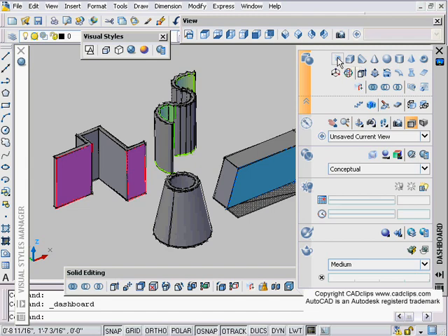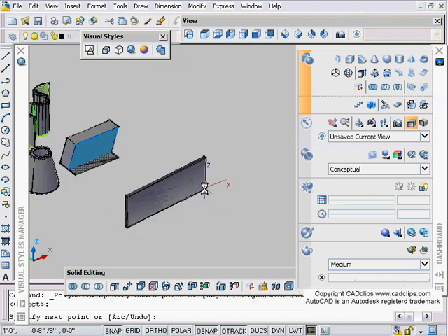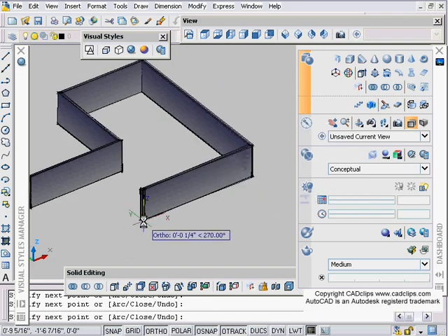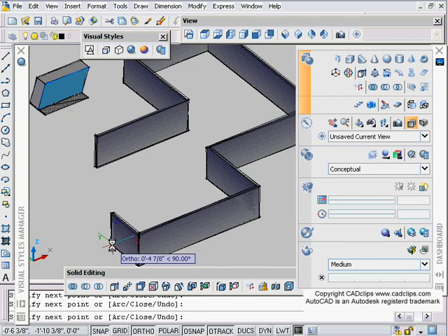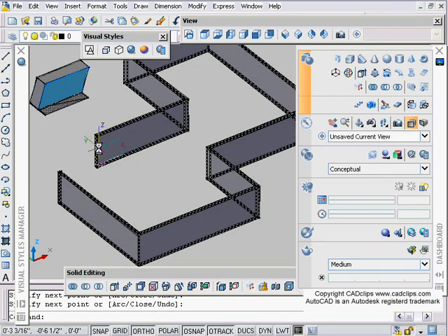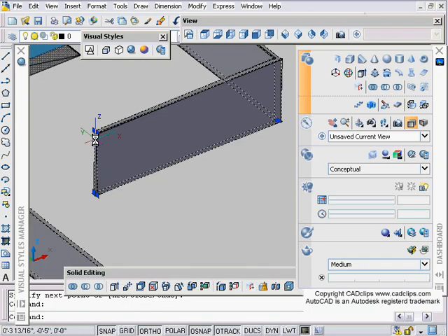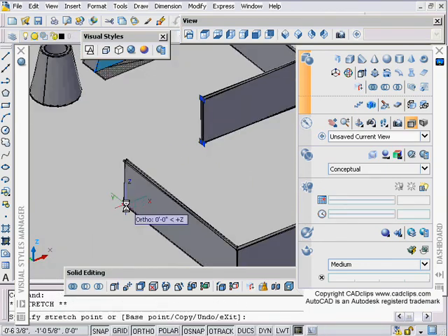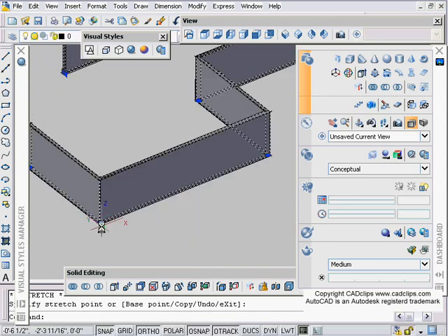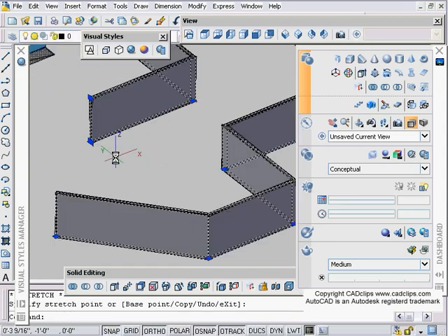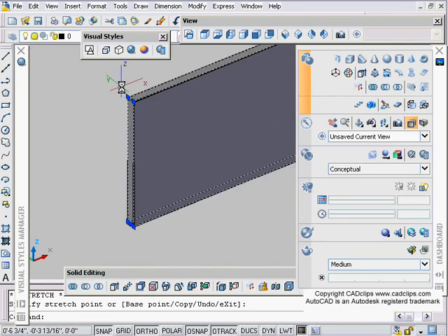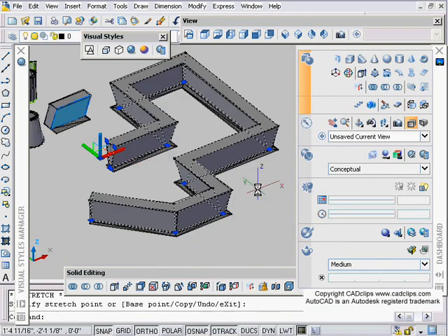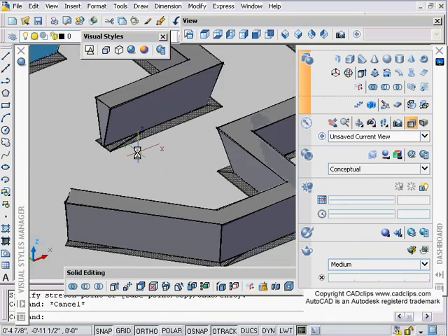Really easy stuff, and if you want, you can just pick Polysolid and start to draw. You can use your ortho, etc. Polysolid just kind of draws walls in its natural state. Once you have that, you'll notice that at the start you have some special grips. First of all, you can grip on here and stretch that this way. This one will stretch this way, and then we can stretch using good old grips that way. The other thing is at the beginning of that Polysolid, we can grab grips and stretch these out, and that changes the whole object.